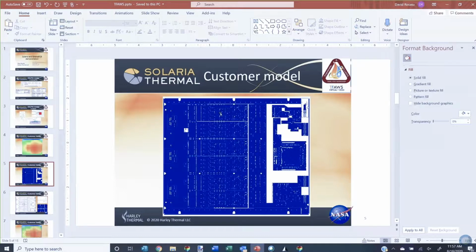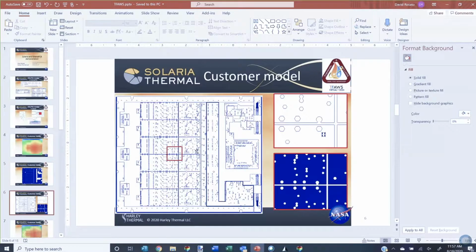Well, fortunately, he was able to send us the Celeria PCB file, and we looked at the different layers. We saw these blocks of copper. Okay, and we looked at lots of the layers, and they were all identical. And when we looked even closer, in this area, there's these splits. Again, they're at different voltages, so they create these splits. But the unique thing about it is all the different layers, all the splits were right on top of each other. They were all identical.